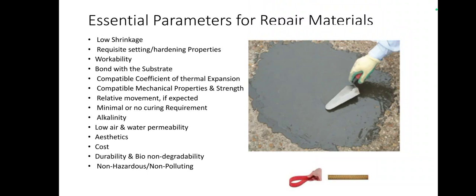So we have to extend its setting time, which means we have to slow down the reaction. For that, some chemicals and some repair materials are available to increase the time of setting. The next one is workability. Whatever repair material I'm choosing should be workable also. From a strength point of view it may be very good, but if it is a very solid material and we can't work on it, then that material should not be used for repair purposes. So it should also be workable.